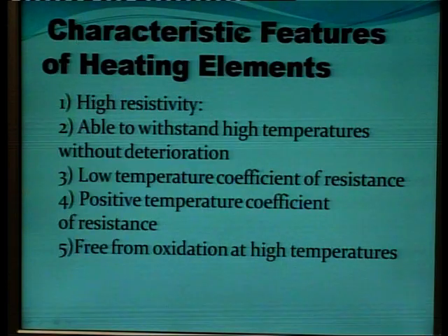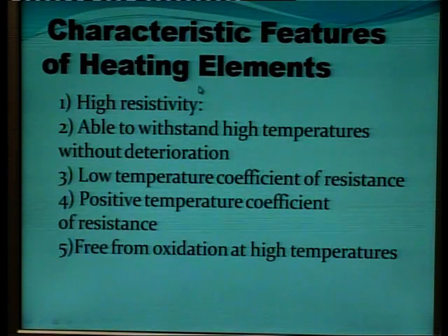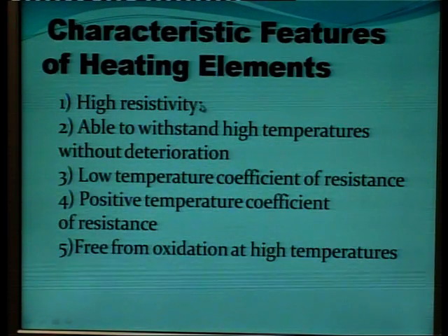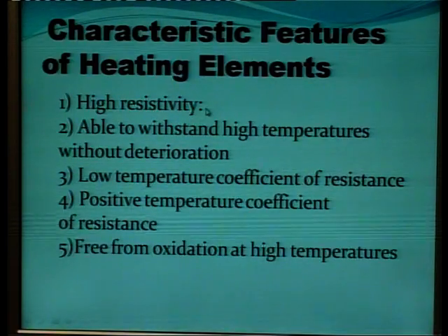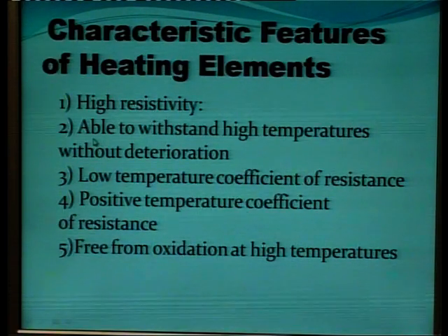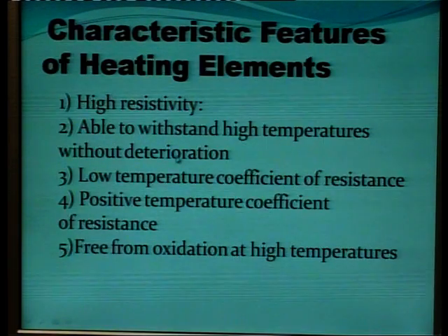So characteristic features of a heating element: first, the heating element must have high resistivity. High resistivity means it requires a very small wire to obtain that temperature. Second, it must be able to withstand high temperature without any deterioration.